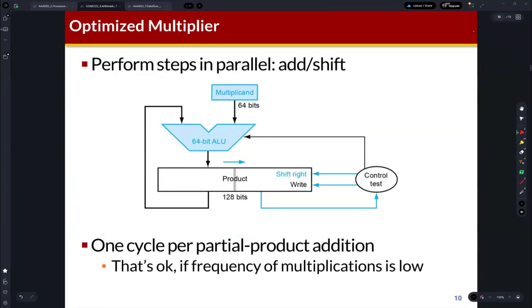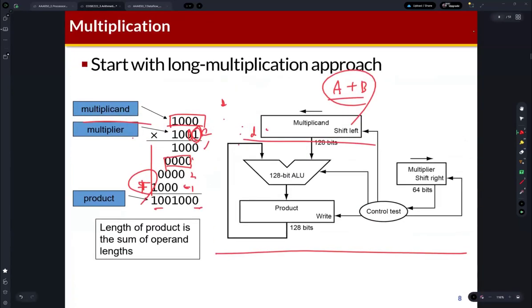So this is a diagram of a multiplier. As I mentioned, we can implement the multiplier using shift operations, but it's too slow, right? For example, using this hardware, firstly we generate the first partial product, and then we generate the second partial product, and then we perform the shift operation, and these partial products are accumulated.